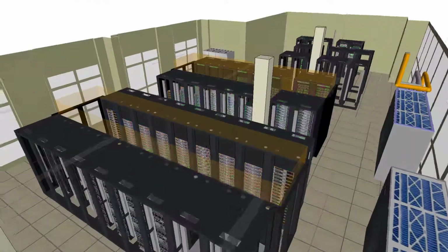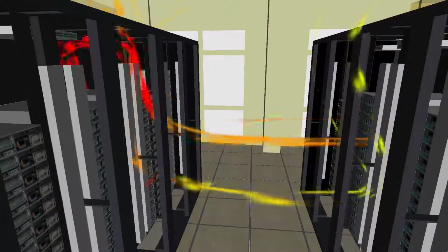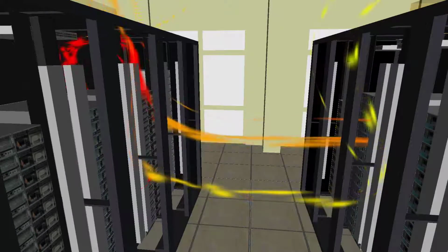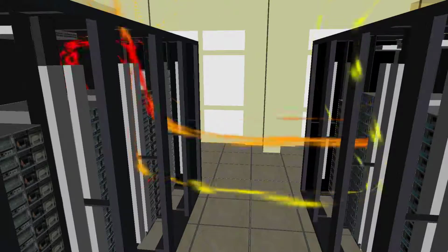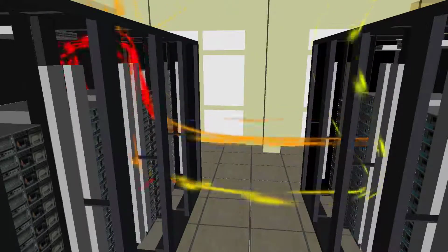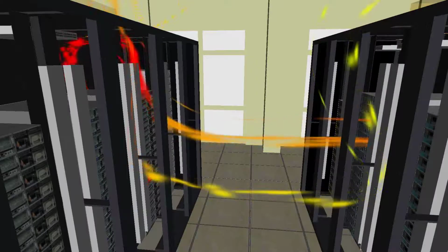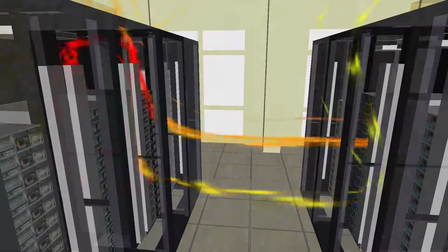Without simulation, the only option for meeting the capacity needs of the servers was to provision more cooling capacity from the room. But with Digital Twin, the root cause is clear. This is a local airflow problem, not a room-level cooling problem. This problem can be solved without having to provision more cooling capacity. This can be seen more clearly by isolating the cabinets that are interacting with each other.